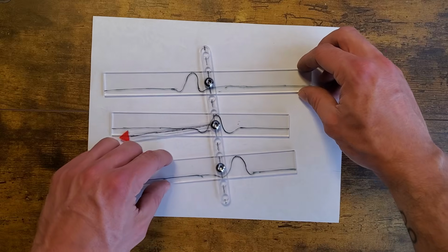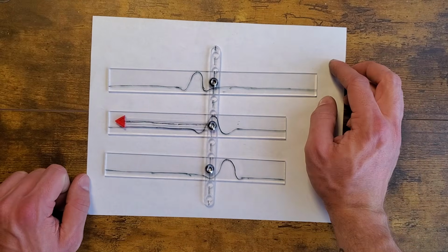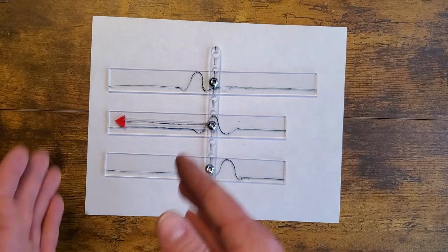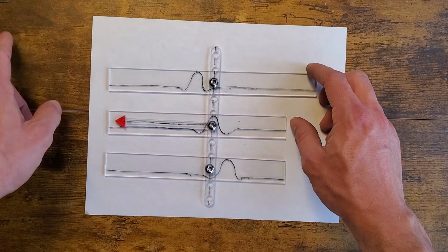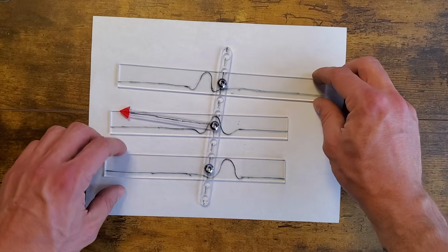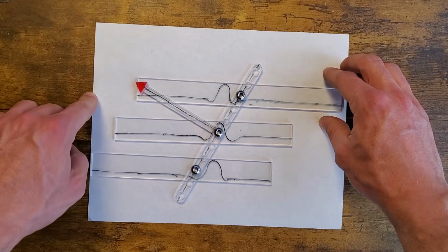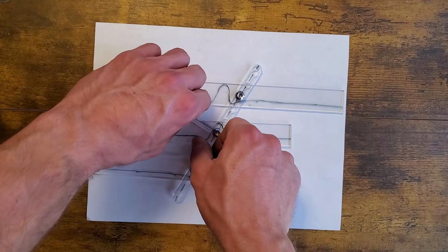And to render a pixel directly in front, we don't have to do any shifting at all because this line's already vertical. This basically offsets the data based on the expected time of arrival of the signal. So if we expect that the source is up here, then we would expect that the sound would get here first and then here and then here. So we shift it to line all of those up vertically.